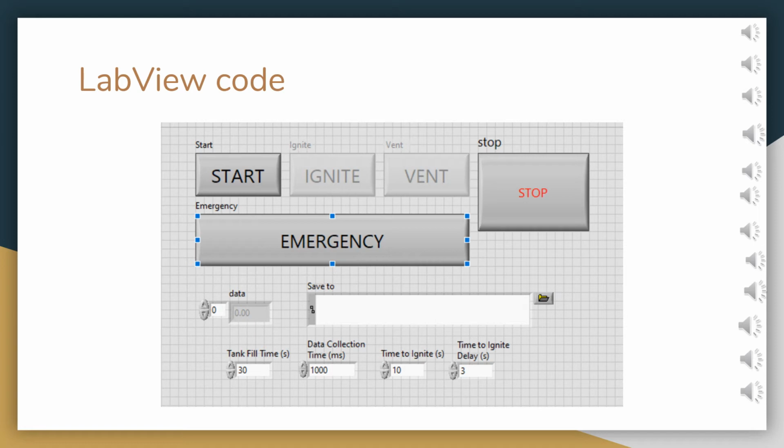There is an emergency button. When pressed, it will take current away from all the valves, which will open both the vent and the emergency valve and close the inlet valve. This is done to vent any hazardous gas into the fume hood and release any pressure buildup in the system. This button should be pressed if some tubing has been clogged or if the experiment needs to suddenly stop.